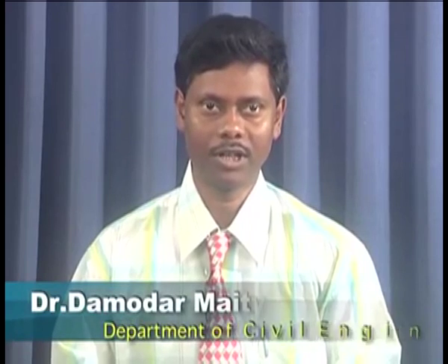Hello, today we are going to focus our lecture on lacing for built up compression members. In last lecture we have just introduced the lacing systems. Why is lacing required? As we told earlier also, to make the built up section act together, we need to tie the built up members in such a way that they will work as a composite. That means when the magnitude of load is very high, then we need to introduce built up compression members because of unavailability of higher sections.